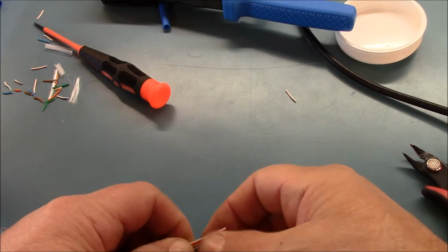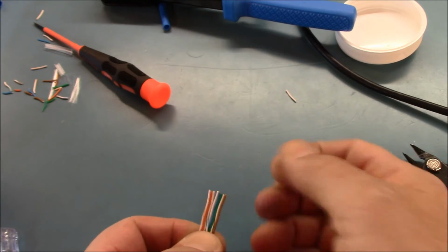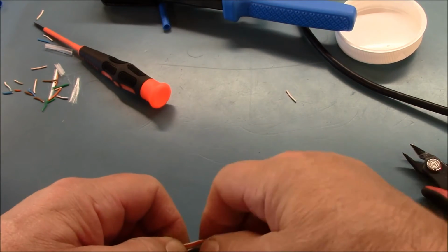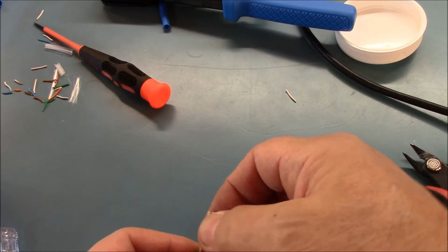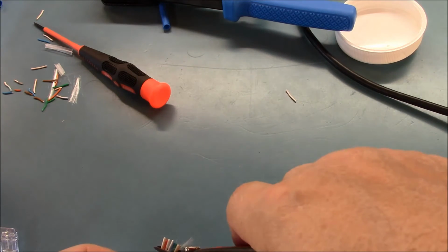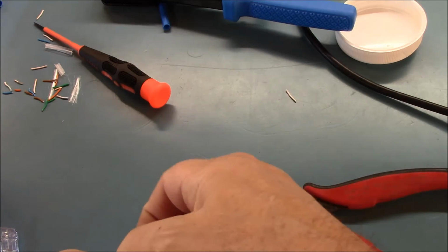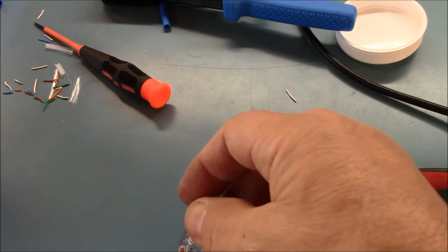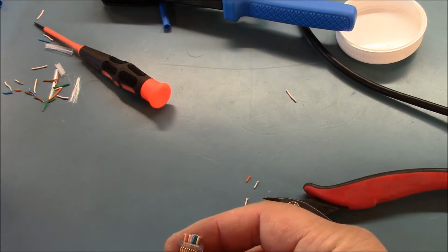One thing to remember while you're doing this, and I actually ran into this myself, so I wanted to show it to you, is you need to make sure that when you get ready to put the connector on, you leave yourself plenty of room to hold on and keep the wires straight, because they need to be very straight going into the connector, and that's any of them. So when you get ready to put that connector on, they need to be in almost perfect alignment, and then you stick the connector on like that.